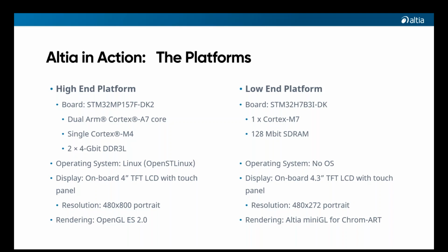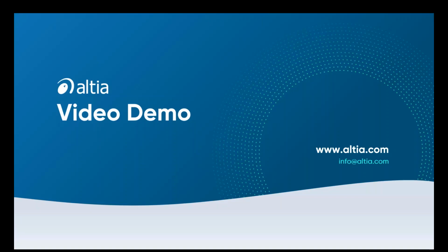The low-end platform we'll be looking at is the STM32H7. It's a single Cortex-M7, more resource constrained, but you'll see we still get a great product out on a 4.3-inch TFT, and this is running bare metal, no OS. For the rendering, we will be using Altia MiniGL coupled with the Chrom-ART 2D graphics engine.